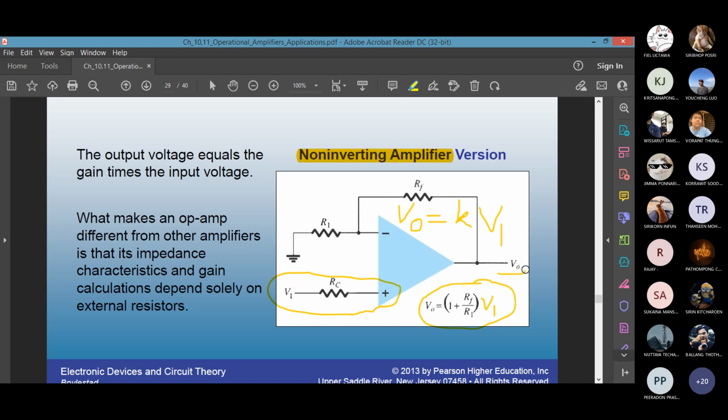This output voltage you can feed onto the other part of your circuit. Maybe you're doing a project, using this V out as a source to some other stage. So this is a voltage source controlled by an input. The resistors are fixed. I can change input voltage V1, maybe 10, 20, 15, according to my wish. This becomes a voltage controlled voltage source. The controlling parameter is V1, which is a voltage. The voltage source which is controlled is V out.